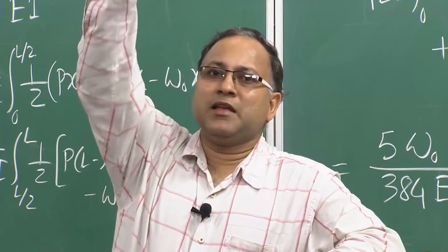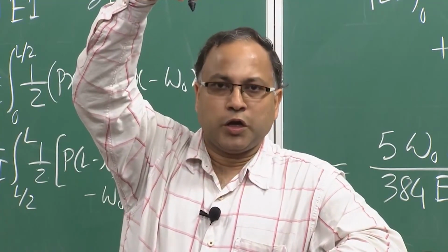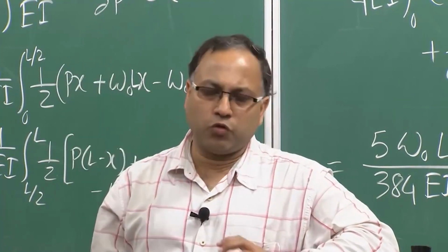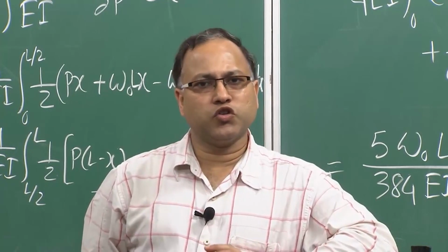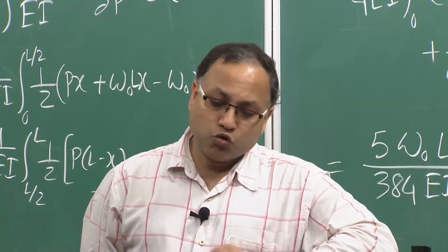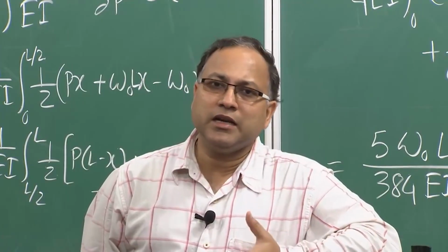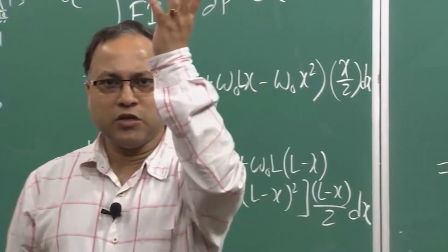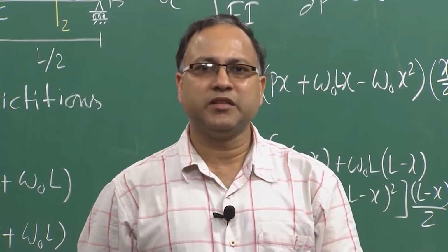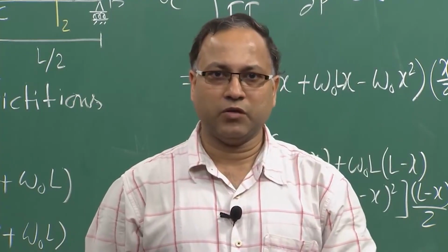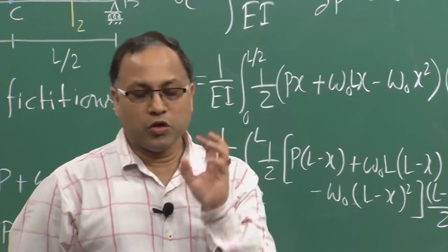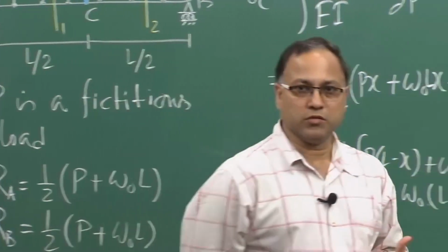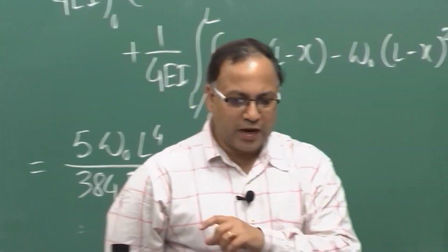Now, if you apply the load on the column, at a certain magnitude of the vertical force, the column will not show any kind of instability. As you go on increasing the load, suddenly you will see that the column will be buckling, right, and that is causing the instability in the column at that particular loading. Okay. So, we have to find out that load where the instability gets initiated, and that load is known as your critical load. Okay. So, let's talk about that.